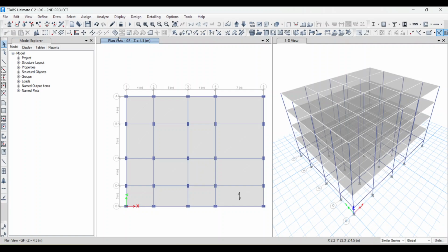So what will happen? I am on the ground floor now, and I will select the slabs. Here you see the slabs are selected up to this floor. But this is not our part. Now I want to put the wall beam loads, that means frame loads. We calculate the wall loads, and the wall loads will come on our frames, and beams are called frames by ETABS.